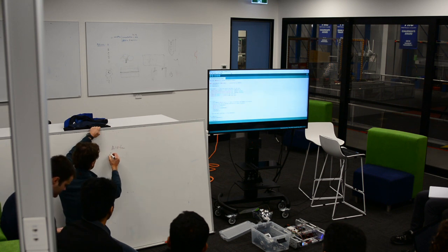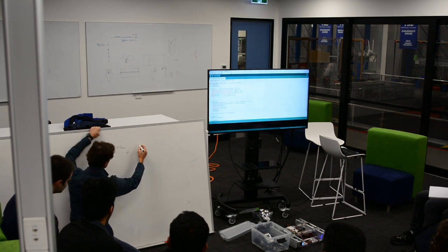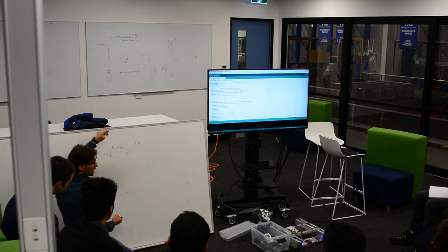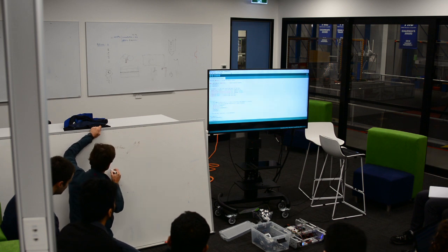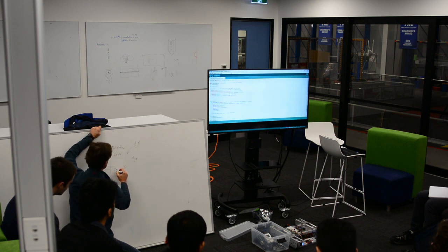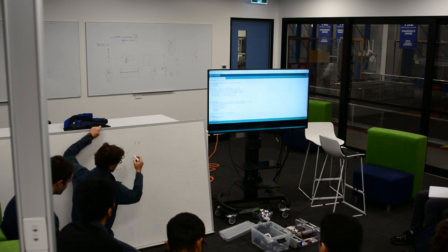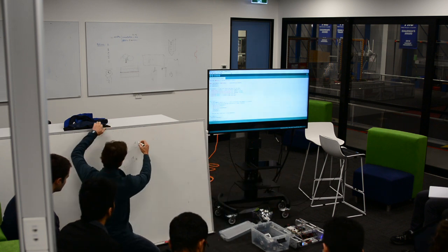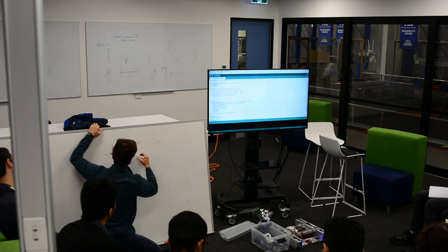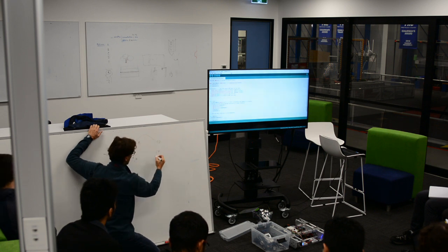So we've got our motor, and on the back of that is the interrupt. Now I'm just going to draw the A and the B line on the interrupt. We're not worrying about the power and ground and all those other things. We actually have two motors, so there's two A's and two B's. We'll call this the left, and we'll call this the right. If you look at the Arduino pinouts, 18 and 19 are interrupts. So I'm going to take A to 18, and I'm going to take this A to 19.